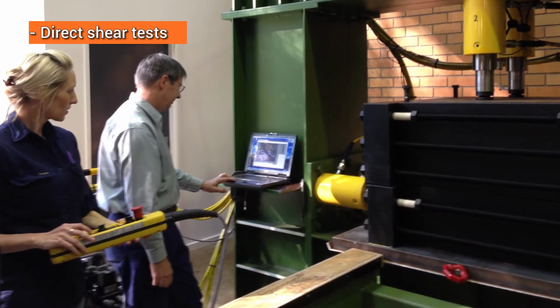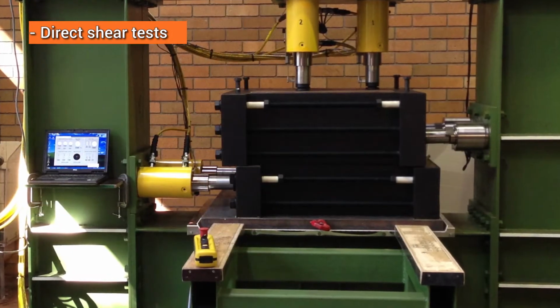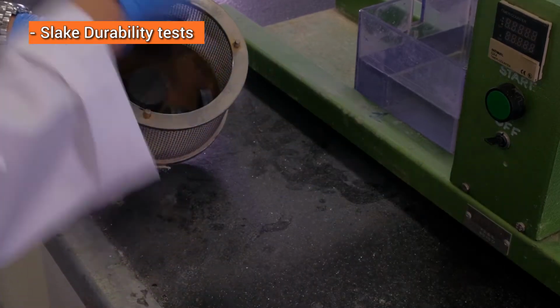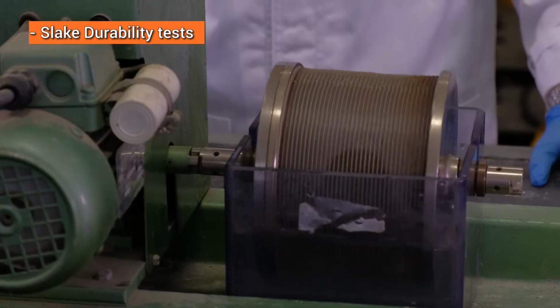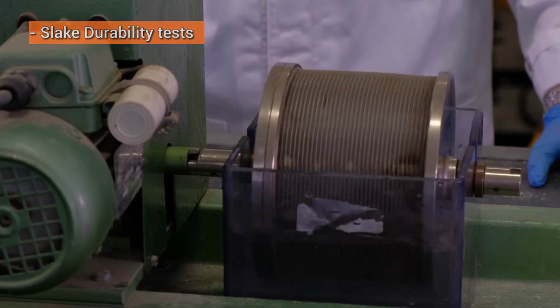Direct shear tests are required for the determination of defect strengths, for example, shear planes, joints, and bedding planes. Slake durability tests are required for the determination of susceptibility to degradation when exposed to water. These tests are particularly important for understanding how waste material will behave in dumps when exposed to water over long periods of time.